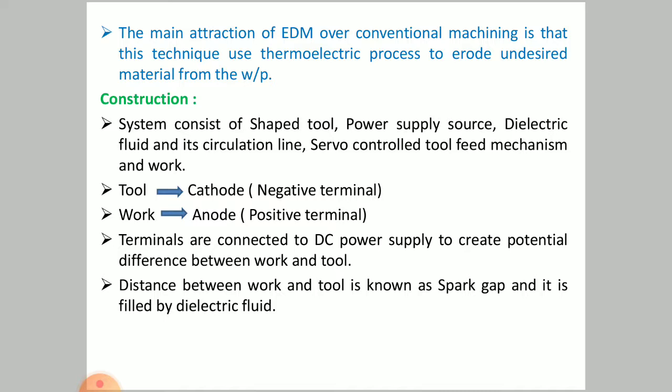Then power supply source, dielectric fluid and its circulation line, servo control tool feed mechanism to maintain the gap between the tool and the workpiece, and of course the workpiece. One thing which should be mentioned importantly is the dielectric fluid that plays a vital role.